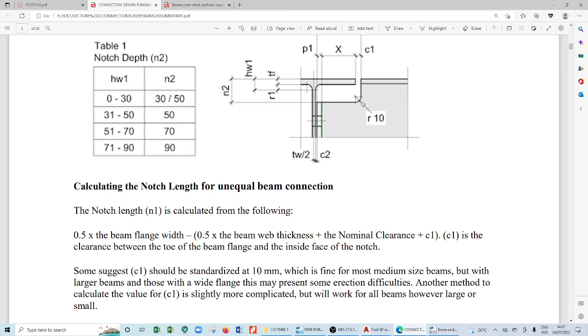This yellow one is an extract from one of those manuals where you have sections with their properties documented. They give you the weight, they give you these dimensions, the height, the radius here, the thickness. That's why I call them standard sections. So when I ask for 203 by 103 by whatever weight, I go to the table straight away.